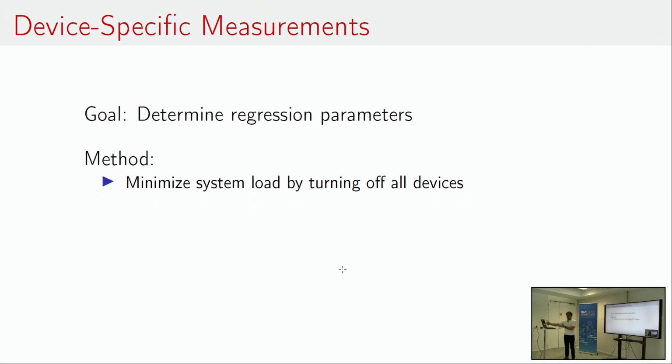We're doing something quite similar here. We have 1,000 devices in this system running simultaneously. All of them have a single input, the battery. None of them give me the information that I need. This information is simply not available, neither in data sheets nor in the system. So how do we solve this? We turn off everything. We measure the static rate, and then we turn them on one by one.